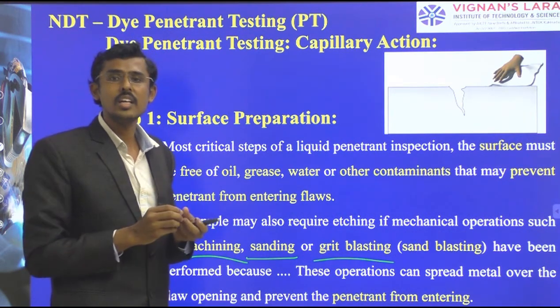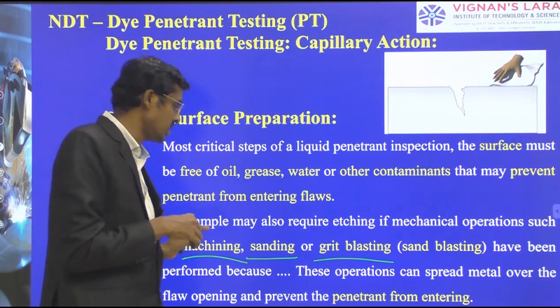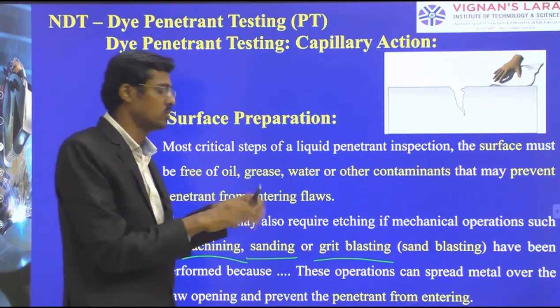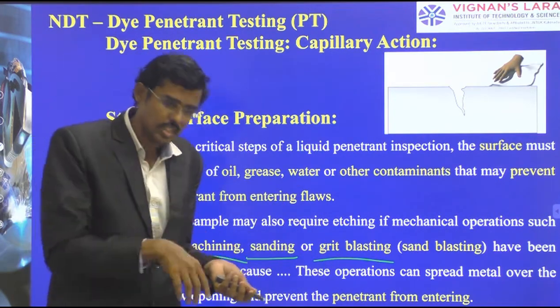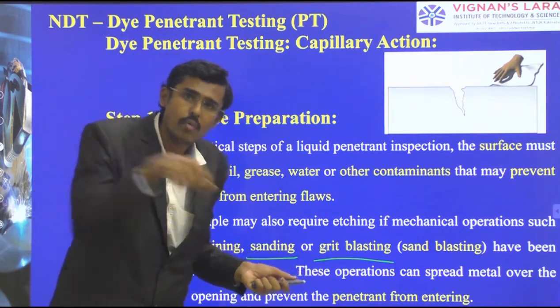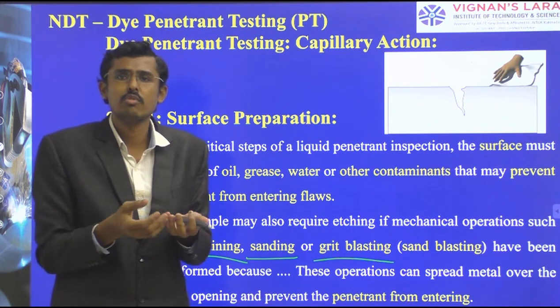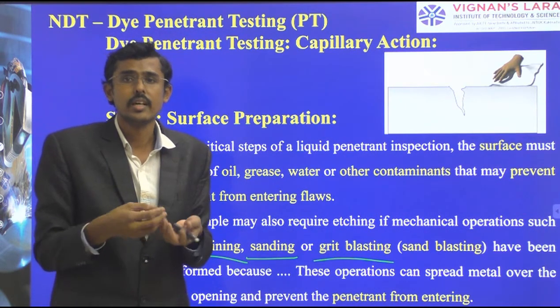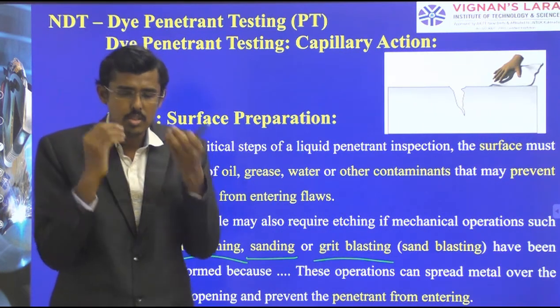If the surface is not cleaned before inspection, the material that comes out of machining, sanding, and grit blasting or sand blasting will remain on the surface. When we apply the penetrant over that, it is going to block, and therefore we are not able to inspect those cracks.